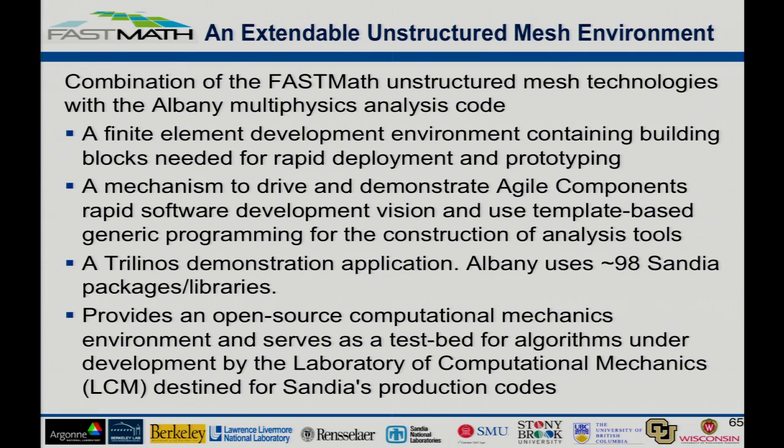For example, residual functions that you can use to form the actual residual of the physics system. Then you can use a forward AD mechanism to form a Jacobian, basically a quote analytic, unquote Jacobian, based off of using that residual function. And then you can continue on and form all manners of other types of derivatives, tangent matrices, uncertainty quantification derivatives, etc.